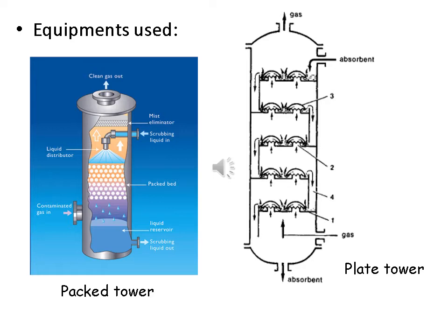Packed tower is a commonly used equipment. This equipment consists of different parts. The major parts are the tower packings, tower internals, then the tower, the pedestals, padding, supporting part, liquid distributor, gas distributor, etc. Detailed figure given in the next slide.